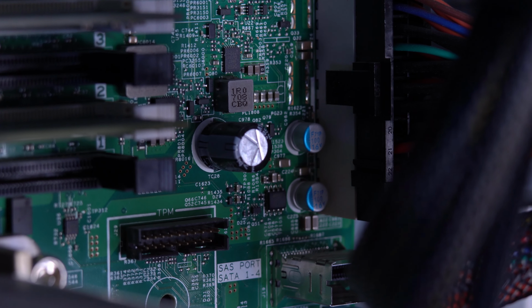Even if you have a perfectly designed and constructed computer that only experiences bit flips from cosmic rays, the exact frequency of bit flips will depend very heavily on the amount of radiation shielding. The ability of radioactive particles to penetrate into shielding is a very well-studied science. Simply having a layer of steel or concrete between the computer and the sky would have a dramatic effect on the rate of bit flips due to cosmic rays. Most of these quoted statistics don't say anything about what floor the computer was on, or what the roof was made of. These are very important variables for determining the frequency of bit flips due to cosmic rays.